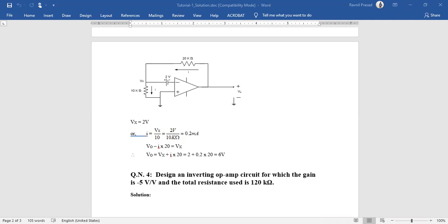Okay. So remember again, I'm just going to repeat this again, that you just need to perform your nodal analysis over here, right? Just at this particular point. Because there shouldn't be any voltage difference going across this op-amp. So this particular point, just after the negative terminal of this battery, is basically grounded. Or there's 0 volt going into the negative terminal of this operational amplifier. So that is why we have directly 2 volt being supplied at Vx, right? And you can directly solve this if we know that.